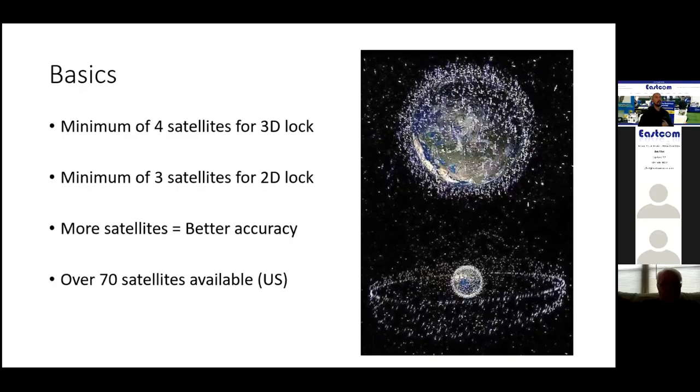If you're standing out in the field and you say, okay, front left, front right, back left, and you look at your surroundings and you've got a lot of things blocking these satellites, if you want the best accuracy that you can get, you need a view of all 4 of those quadrants. If one of them is blocked, you're not going to get the best accuracy. That's the best way I can put that.